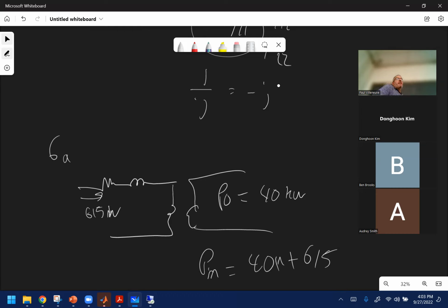That's it. You had to multiply 50 kVA by 0.8, add a couple numbers together, and then divide for efficiency. Remember, efficiency is P out over P in. It is not S out over S in or V out over V in. It's only P. Questions on that? I thought this one would be the hardest one to understand, but it probably is the overall easiest problem to do, right?